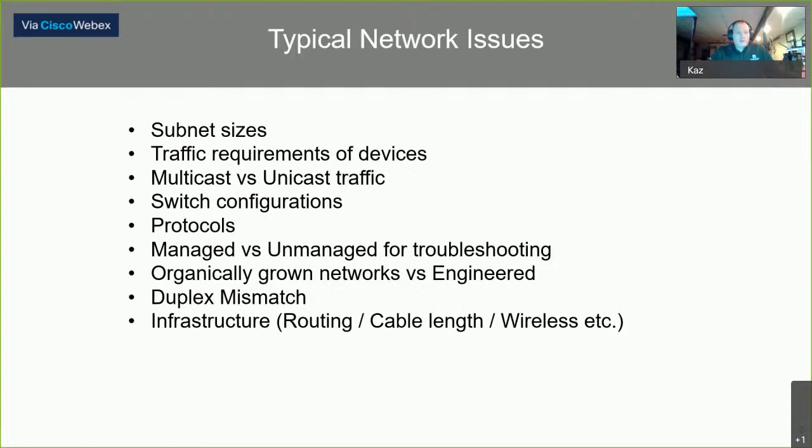Protocols, knowing what protocols are on the wire is also important. You wouldn't want to put something like CIP Motion across wireless, for example, or knowing where your safety protocol, your safety on the network is going, making sure it's not coexisting with other traffic that it shouldn't be seeing.